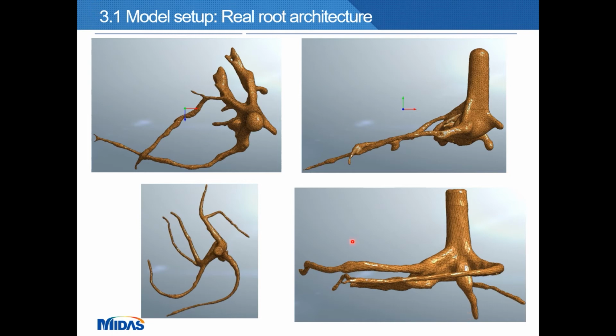In this case, the rooting system of Samanea saman had more structural roots that provide stability to the tree. The average diameter of the first-order roots was about 0.2 meters, or 20 cm. We have 4 structural massive roots in a radial configuration. The depth of the rooting system identified during the test was about 1.2 meters, and the thicker main member of the root structure has numerous secondary lateral roots.